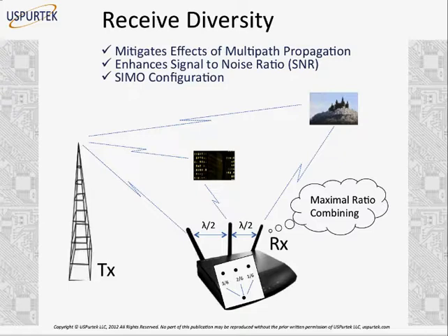And another way I could use is maximal ratio combining, which uses a weighted combination of the received signals based on signal to noise ratio. So the strongest signal has more weight and the weakest has the least weight. So it depends on the carrier or agency who is implementing this while designing the product, and which type of combining gives you the best results for that particular application.